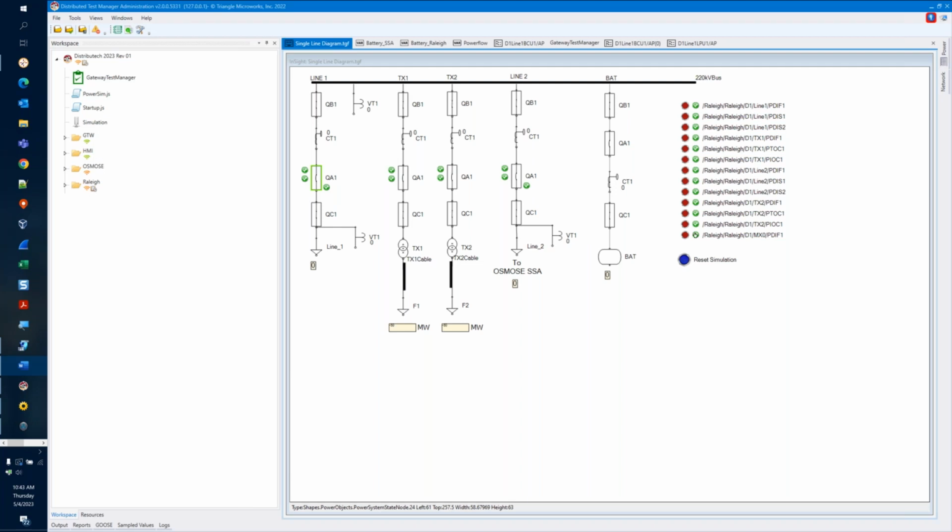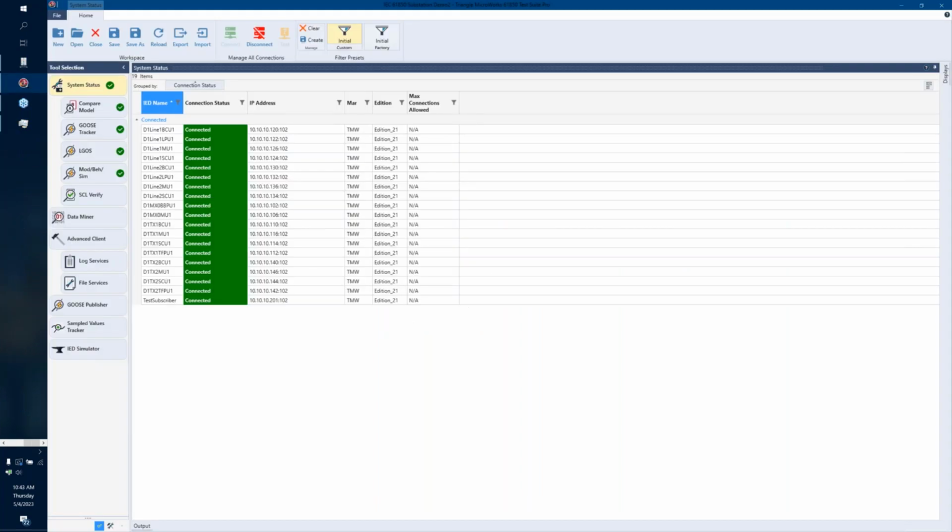Next, I want to come back to the communications drawing equivalent, which is the communications section file of the SCD. For that, I'll be switching over to Test Suite Pro, our 61850 monitoring and testing tool. By loading an SCD file into Test Suite Pro, we can determine the relevant IP information necessary to establish an MMS connection to the different IEDs in our SCD. And that's without any manual configuration or know-how.